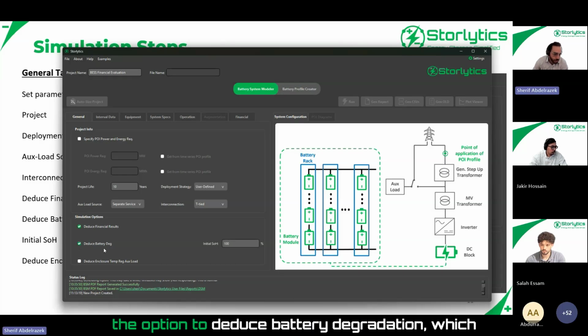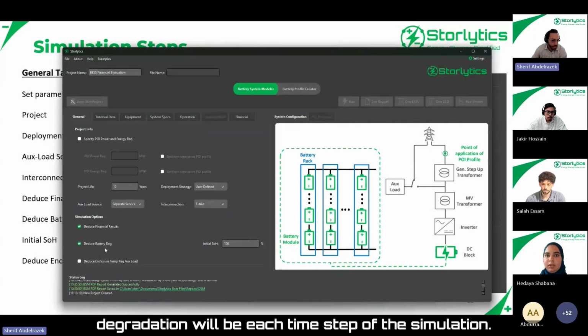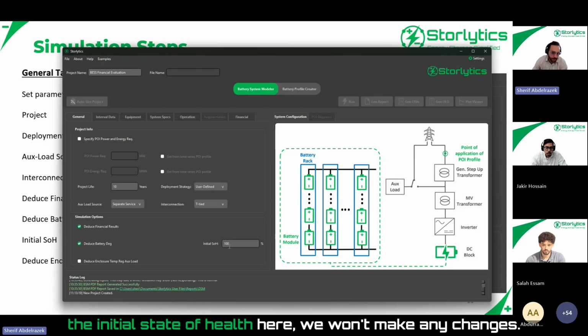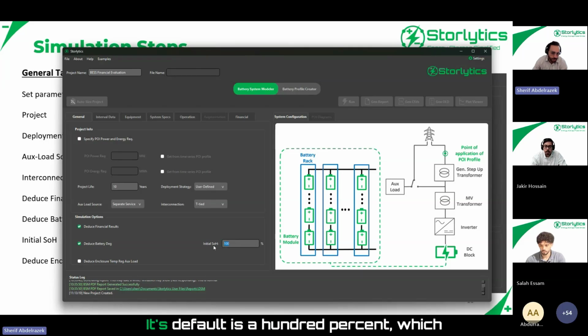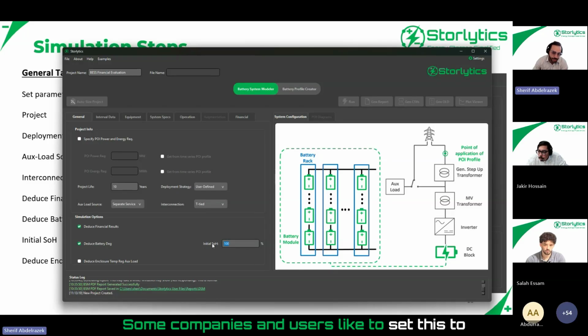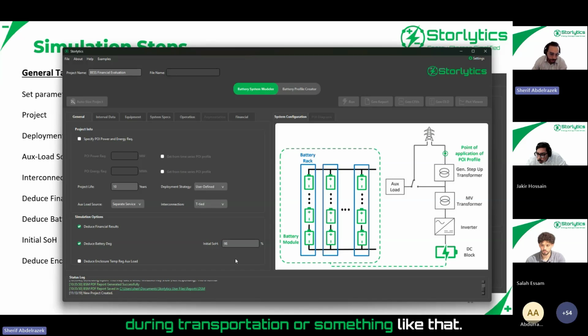We'll also turn on the option to deduce battery degradation, which allows the simulation to calculate what the degradation will be each time step of the simulation based on how the battery system is being dispatched. For the initial state of health here, we won't make any changes. Its default is 100%, which assumes the battery cells are new. Some companies and users like to set this to 98% to account for some state of health loss during transportation or something like that, but really depends on your case here. But here we'll set it to 100%.